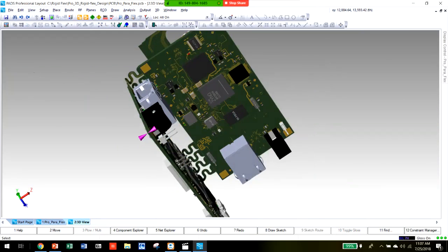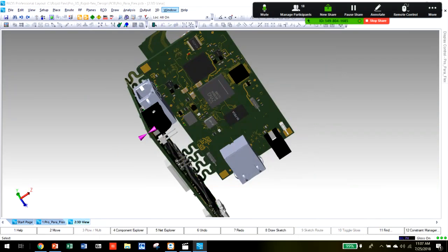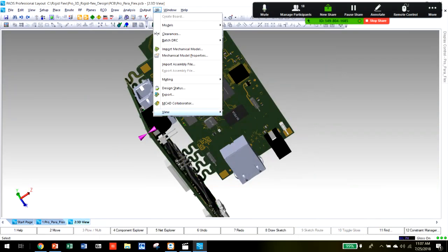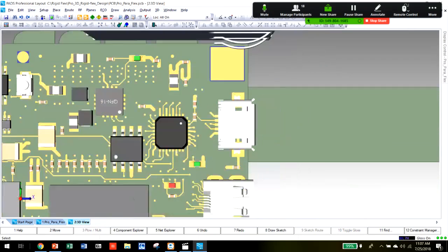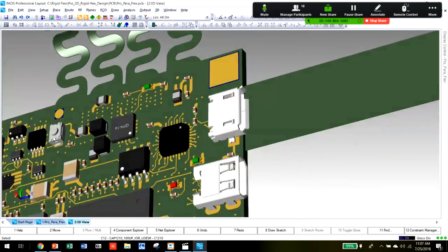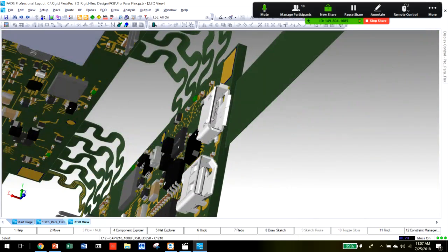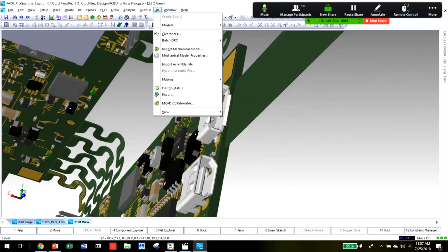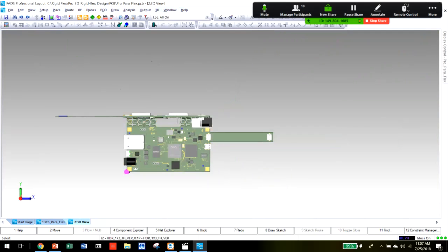And then with that, we can actually see what's going on in here. Let's move this window over. 3D capabilities. Let's look at the top. And then let's zoom in here a little bit. Now you can actually see how the rigid flex has been added into the middle of the plane layer, and you can go ahead and create those in any way that you want. You can read in DXF files. It's very easy to be able to add your rigid flex using the tools possible.